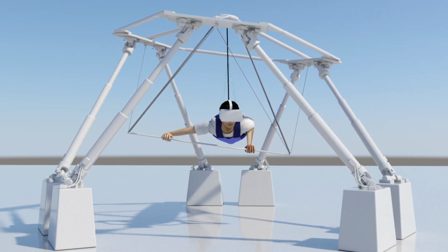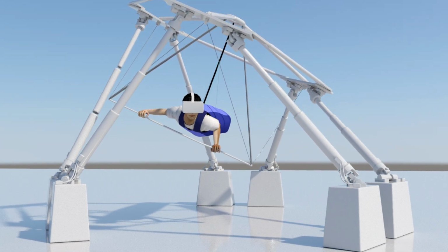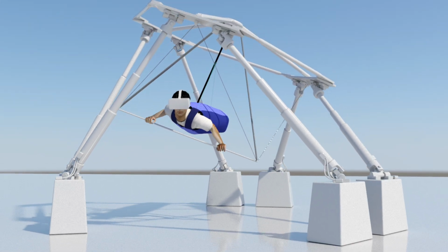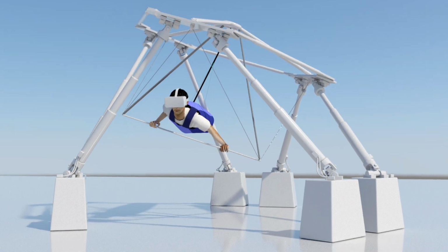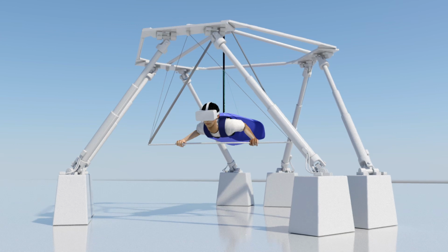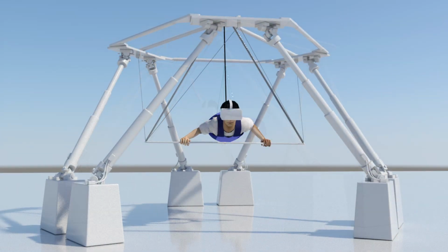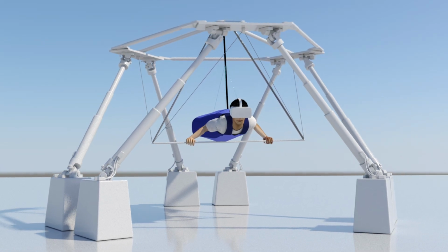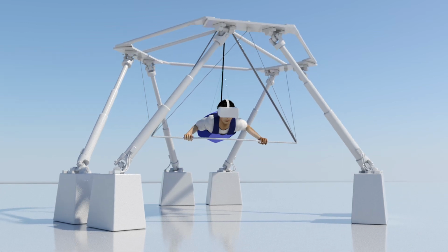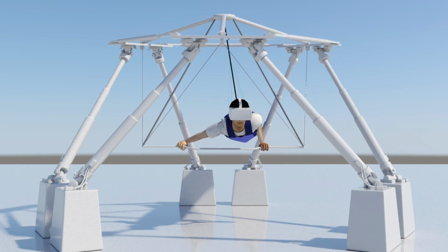And not only can the motion simulator react accurately to steering inputs of the pilot, it can also react accurately to virtualized thermal activity, turbulence and other weather forces. Thermal activity, turbulence and other weather forces can be translated into piston movements, causing the A-frame to react. For instance, a pilot who flies into a thermal can be thrown out of the thermal, just like in a real flight situation. And when the pilot successfully manages to circle inside the thermal, the simulation software will show him he is climbing.